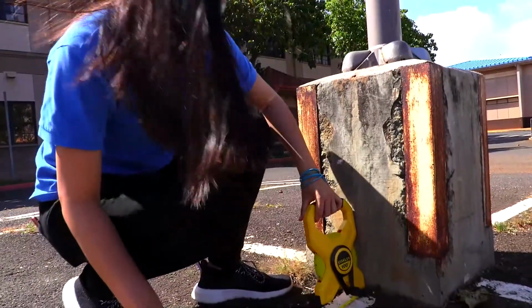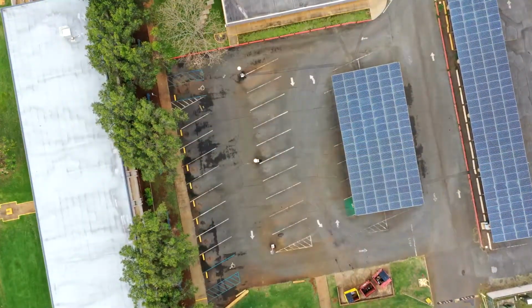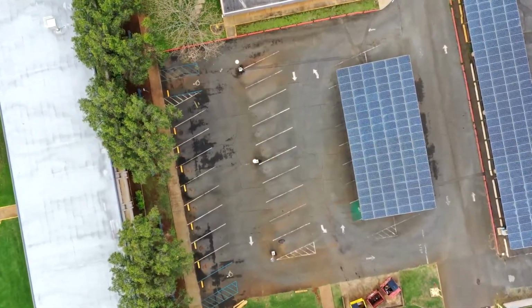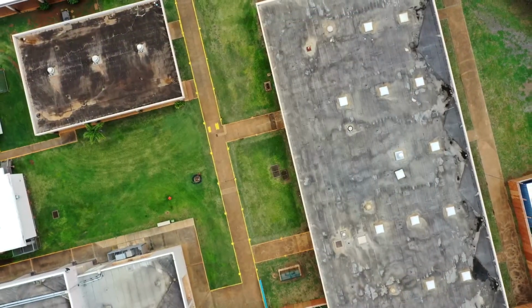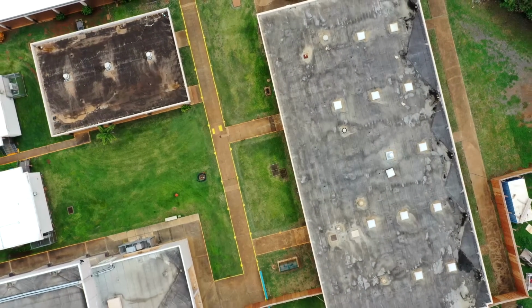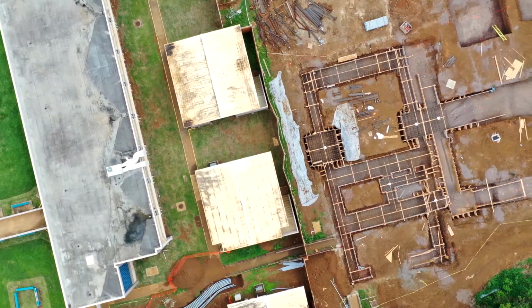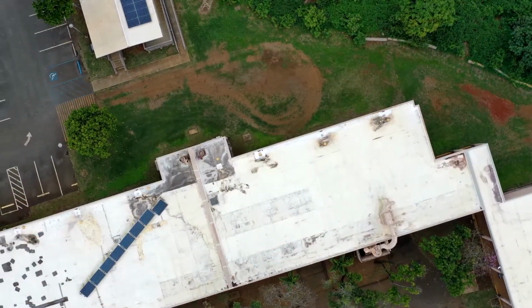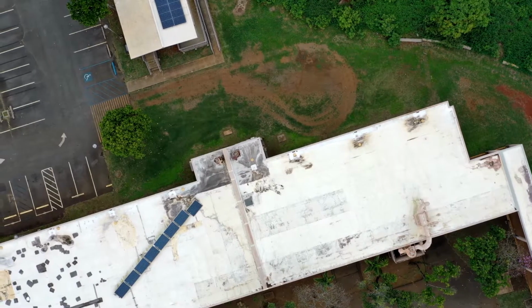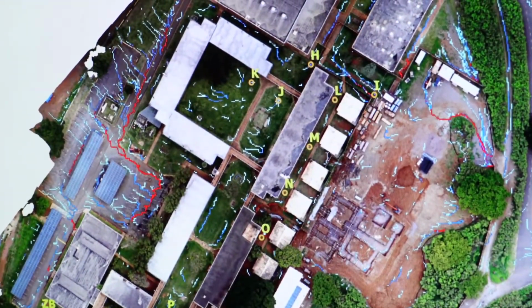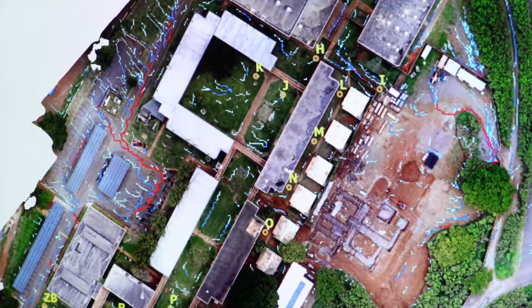and their measurement was to just ensure it was scaled properly. We made them take drone footage, and it helped them with software to get arrows for the stormwater runoff, and that gave us a stormwater runoff map, and within that map we're able to see which areas would be populated with water, and that's where we would implement our BMPs.